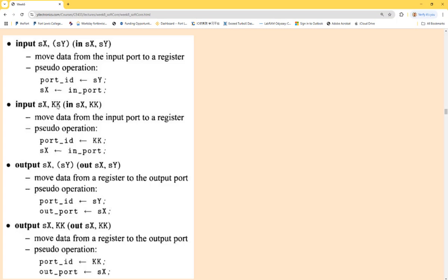given that the PicoBlaze core has 256 ports, where are these ports? And each port is 8 bits, right? And there are 256. So which means you need 8 bits of address to resolve all these different entries, right? So it's eventually 2 to the 8th entries, or addresses, to access all these 256 entries of the ports.